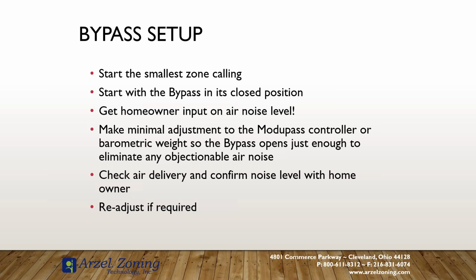But get your homeowner's input, because if your ears are anything like mine, they don't work like the homeowners. And then check the airflow delivery. I needed the numbers, and that's why I checked my static pressure with my meters. And then I let my customer give me some input, and then based on their input, I would leave it alone, or I would turn it back a little bit more for them.